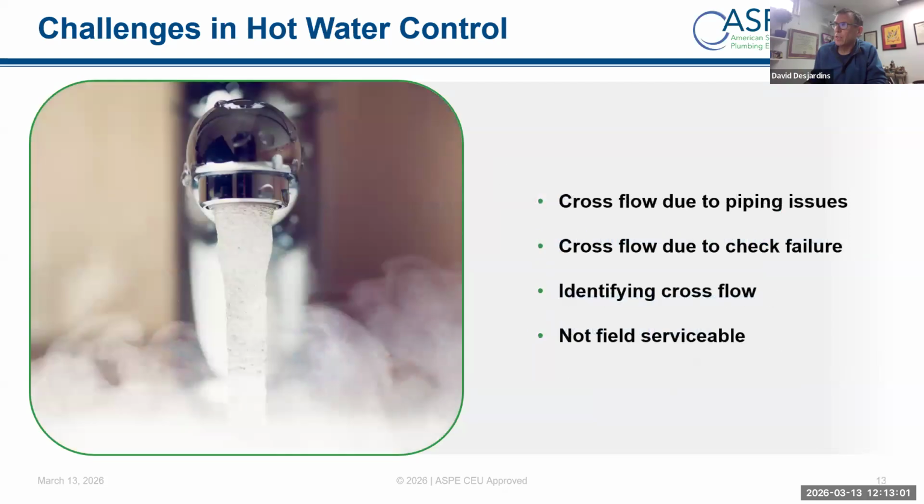The other thing, when we're talking about using hot water or water temperature to mitigate the risk, is that it becomes very clear how important it is to understand crossflow and crossflow issues. Because if I'm keeping one side hot and one side cold, and those two things start intermingling where they're not intended to, or where you think they are separated, right?